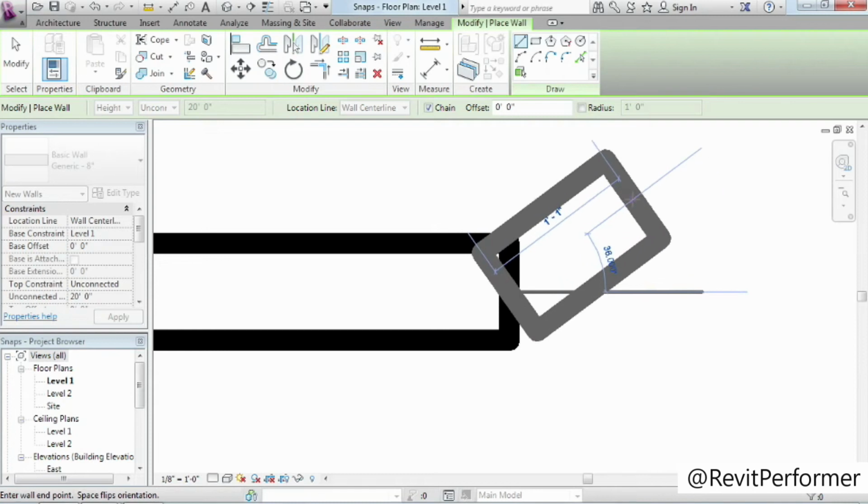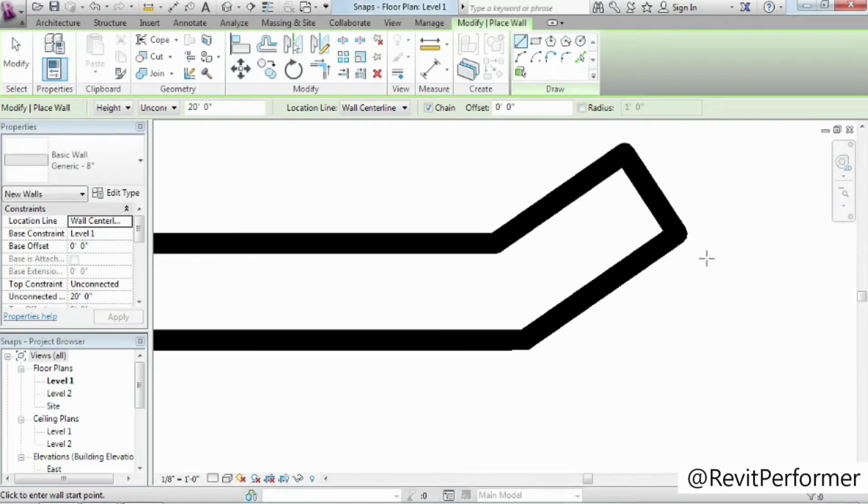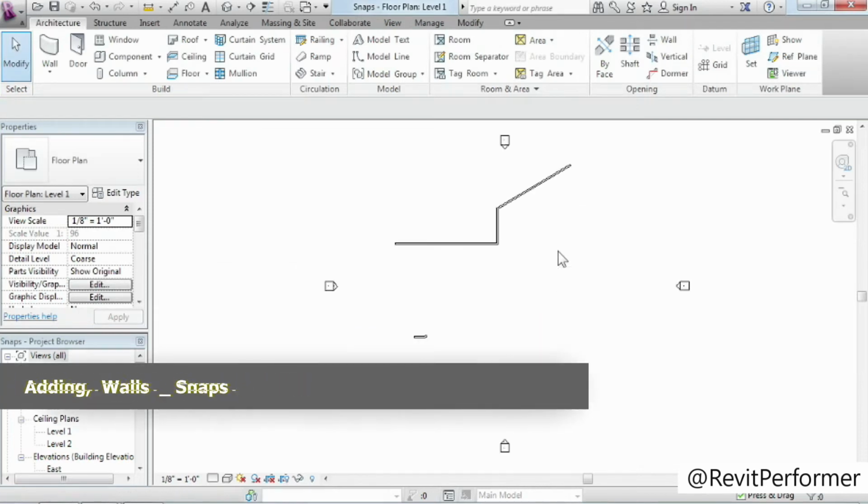So what's really handy about this feature is just simply in the course of your zooming in and out, it will adjust the degree to which it's snapping. So you don't have to go back and change a setting. It sort of does this automatically. Now, where is this controlled? I'm going to do ZF on my keyboard for zoom to fit, just to back out all the way again.